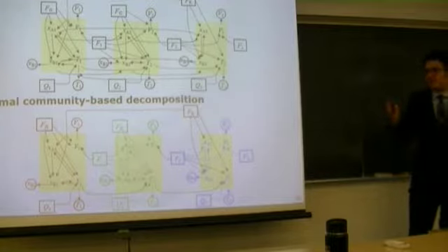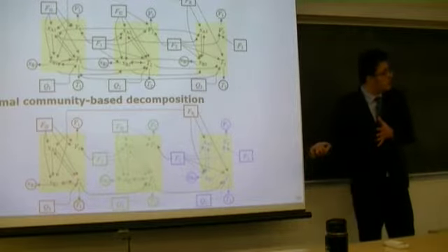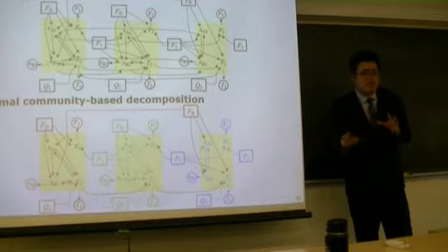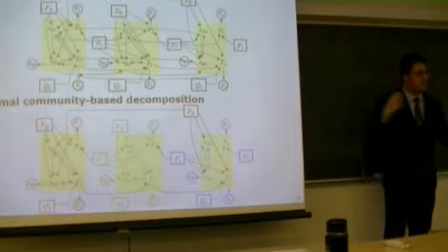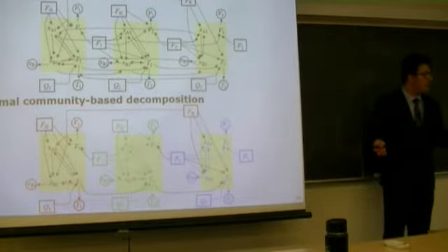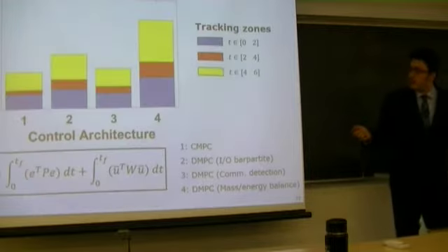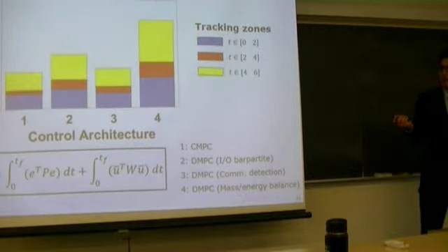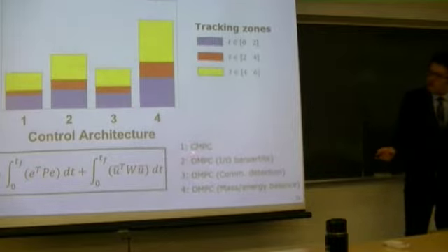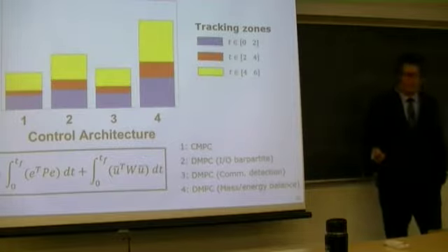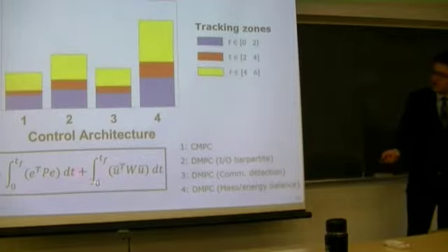So this may seem obvious, since it's very close to the optimal decomposition based on the configuration of the units. But for the more general cases that I will show you next, it's not obvious at the beginning. So to compare the closed-loop performance of distributed model predictive control using this decomposition, we introduce a performance index, which consists, just like a regular objective function, of the tracking error, and also penalizes the magnitude of the manipulated inputs.